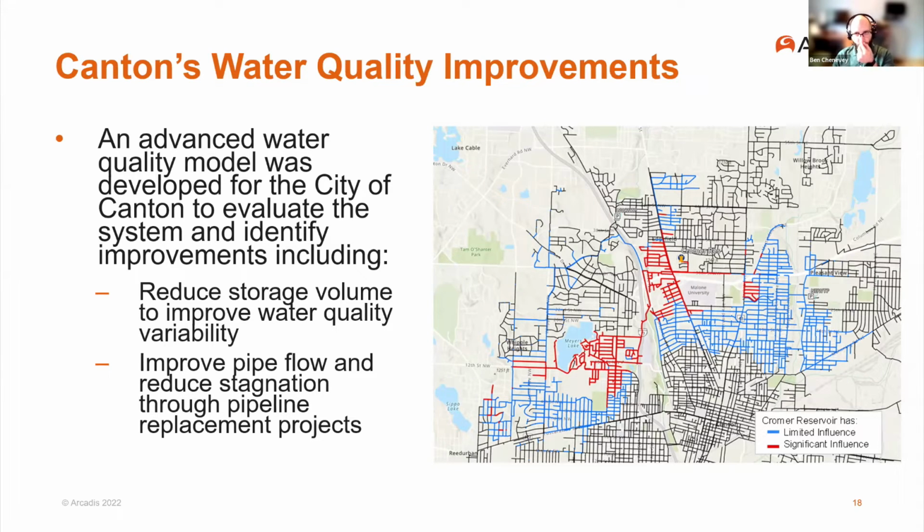For the city of Canton, they don't have a THM issue or challenge out in the system. So we didn't look at things like THM aeration, but that's something that we've looked at for other systems is looking at storage size, looking at operation, but also things like technology improvements. So putting a THM air stripping out in the storage tank, what does that actually change in the system? Can we get a certain percentage removal rate? And can we actually positively impact the THM out in the distribution system? So we didn't look at that with Canton, but that's a common use case for MSX.